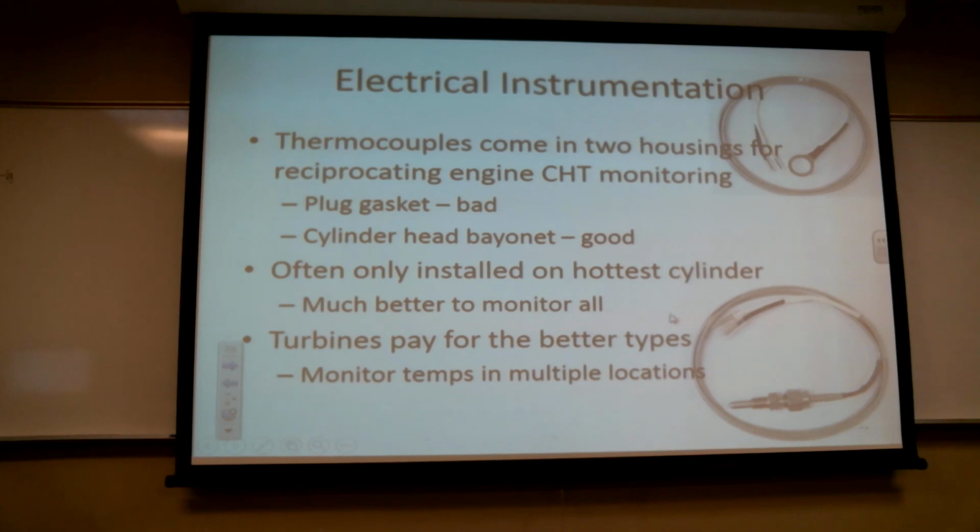Obviously, any turbines or anything like that, it's going to have to be certified equipment. I will tell you, monitoring EGT and CHT is one of the most important things you can do on either a turbine or a reciprocating engine to be able to monitor the health of the engine and monitor it operationally. You really want to be able to set the mixture correctly, particularly for cruise configurations. You need CHT and EGT.